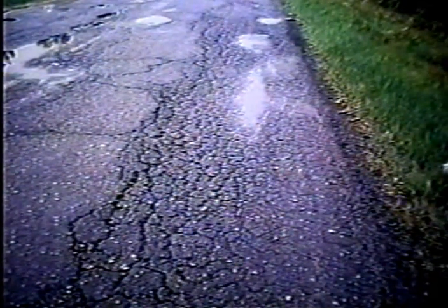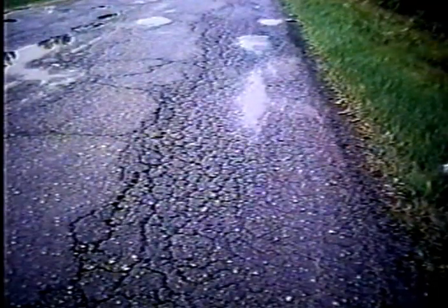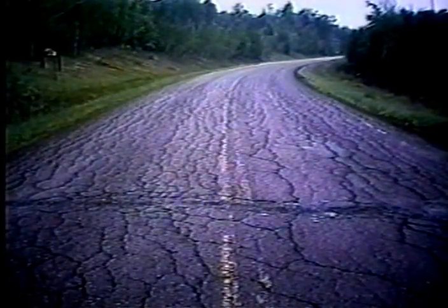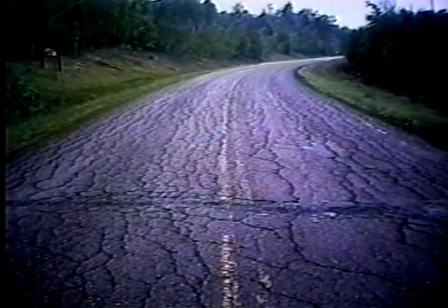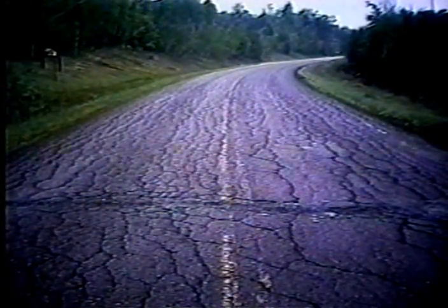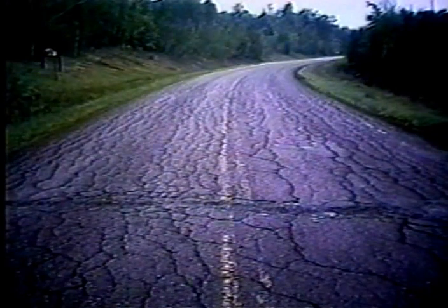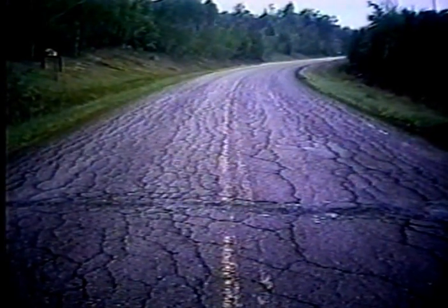Another example of alligator cracking along the outside edge of the pavement, you've got some rutting with water collected in the wheel paths here. This needs to be reconstructed and strengthened. You can't treat this with a surface treatment or a simple thin overlay. Here's an example of a pavement that has extensive alligator cracking over its entire surface. Again, an indicator of extensive aging and heavy loadings and the need for complete reconstruction.